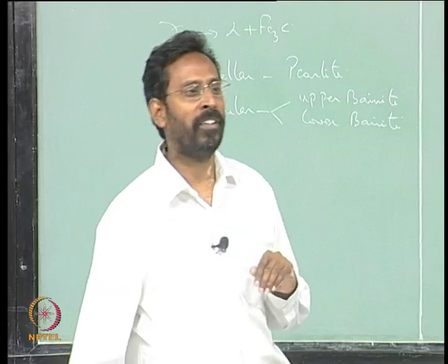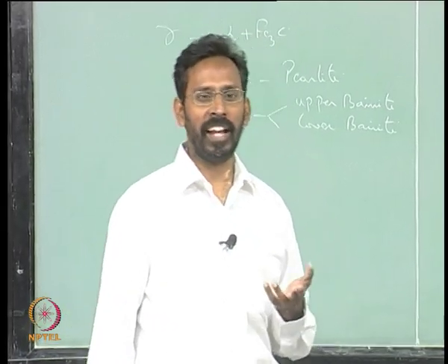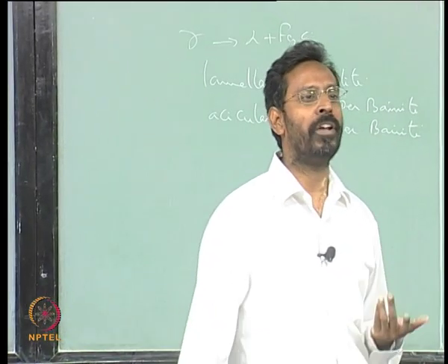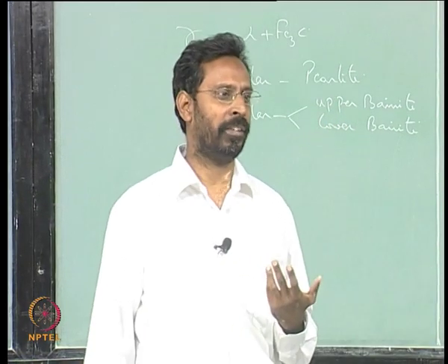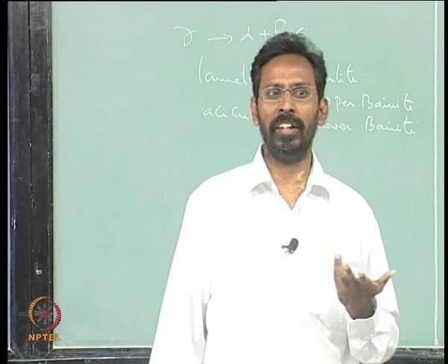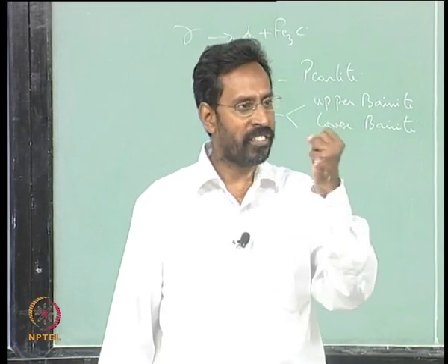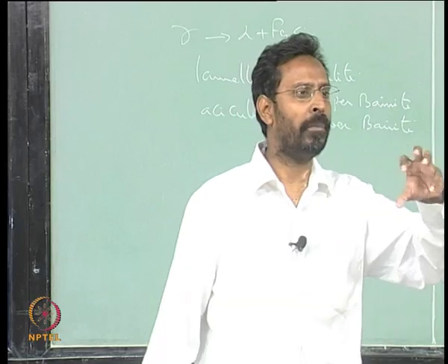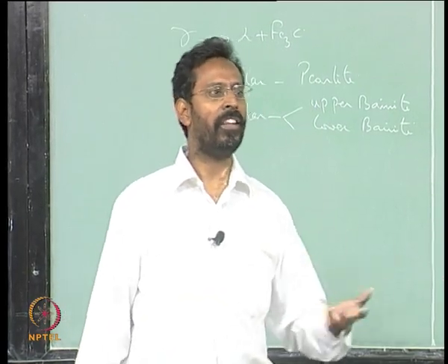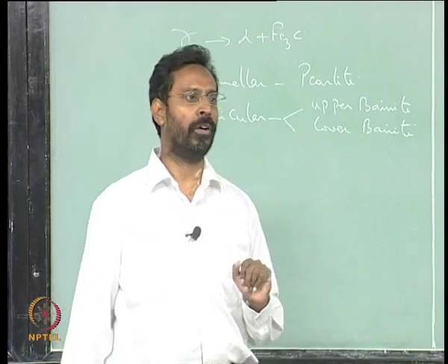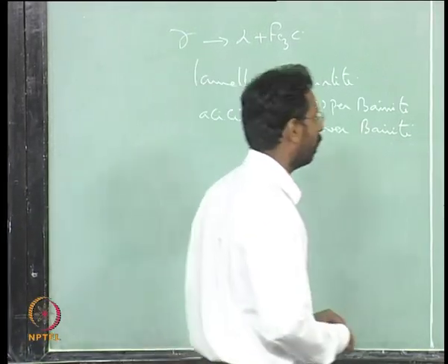Again when we come to Martensite we will talk more about it. Basically again shear is made more difficult, because Martensite transformation is a shear transformation. Whenever you have alloying elements present there, because of the strains that are there around each of the elements that is sitting, you would see the shear becomes more difficult, and when the shear becomes more difficult MS goes down. We will talk about it when we come to Martensite transformation.